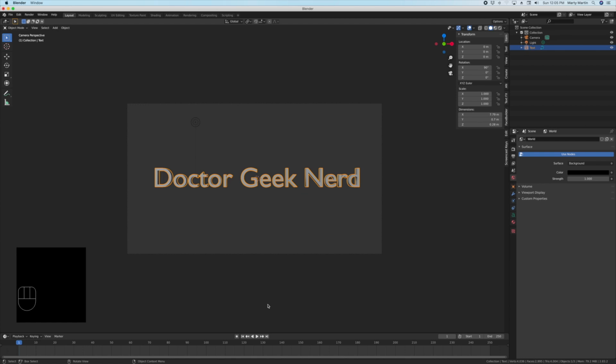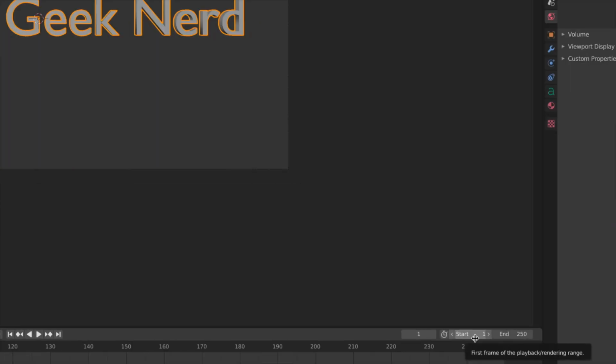That's over a 10-second animation. Let's make it a 3-second animation. Down here on the lower right-hand corner of the viewport, just above the timeline, that's the total length of the animation. It's going to start at frame 1 and end at 250.